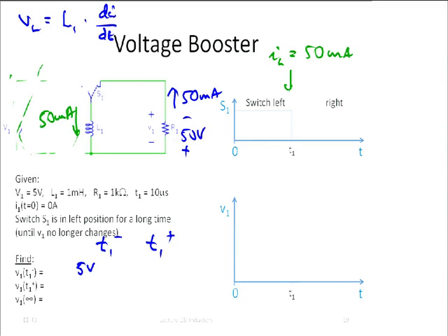So apparently the voltage is positive first, and then it jumps. The voltage you're measuring right there would be 0 before I flip the switch, because that resistor is open circuit. Okay, fair enough. So the main point that I'm trying to make here is that the voltage just after I flip the switch is 50 volts, or actually here minus 50 volts. It's much higher than the voltage was before.